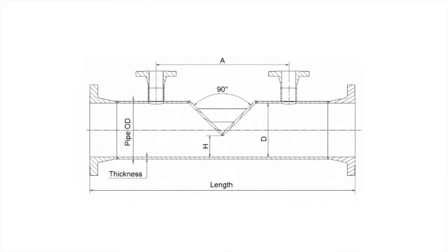A wedge flow meter is a wedge-shaped element that is perpendicular to the flow at the top of the conduit, which means that the bottom part is unrestricted. The basic operating principle behind wedge meters is straightforward. A V-shaped restrictor in the flow meter body reduces the available flow area, constricting the flow. This constriction increases the fluid velocity, causing a corresponding increase in the kinetic energy of the fluid being measured. A differential pressure transmitter is used to measure pressure between either side of the wedge.